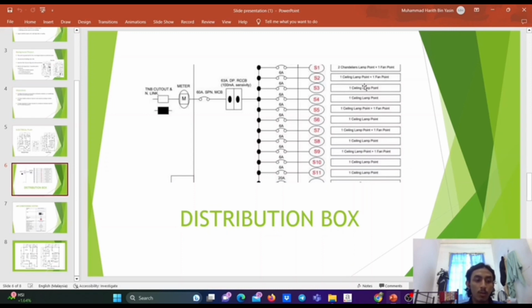Next, I want to tell how a distribution board works. Distribution boxes work by distributing electrical power. They receive electrical power from the main power line or another primary power line and they distribute it via outlets. With a distribution box, circuits won't be overloaded. Circuits of course can only support so much electrical power. If a circuit is overloaded with too much electrical power, it will create a fire hazard. A distribution board works by distributing electrical power while simultaneously protecting circuits from being overloaded.